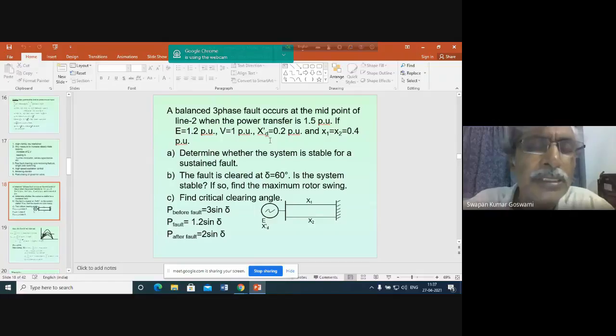As you know, in case of an inductor, whenever you attempt to change current, an opposing EMF is created, an opposition is created. So here also, if you attempt to change the flux suddenly, it will be opposed by the system. How will it be opposed? When the armature current increases suddenly, armature reaction flux will increase suddenly. This sudden increase in armature flux will create an EMF induced in the field circuit of the generator, and an EMF will be induced in the damper winding of the generator.